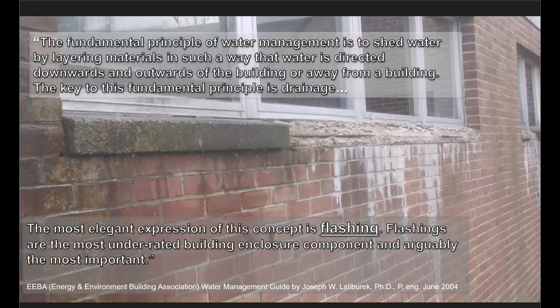Some of you may be familiar with Dr. Joe Lstiburek. He's from the Building Science Corporation. The picture on the screen, yeah, I know it's a little bit of a dramatic looking water destructive photo. However, it's not uncommon for this to happen. You see the efflorescence under the wall or under the window there. Dr. Joe says we have to make sure that we are layering our materials so water can get down, out, and away from a building.